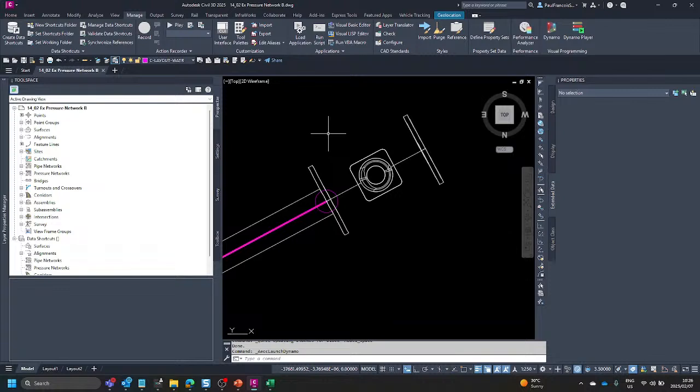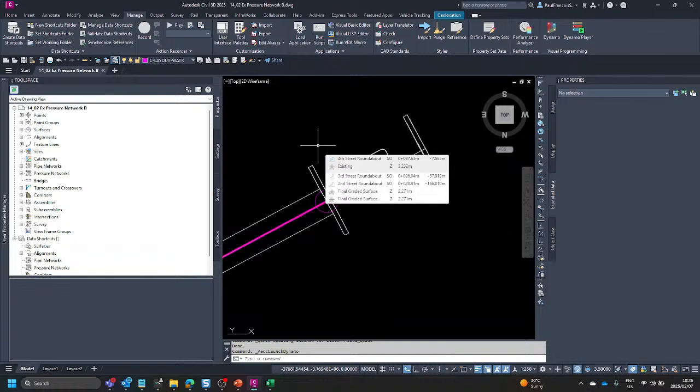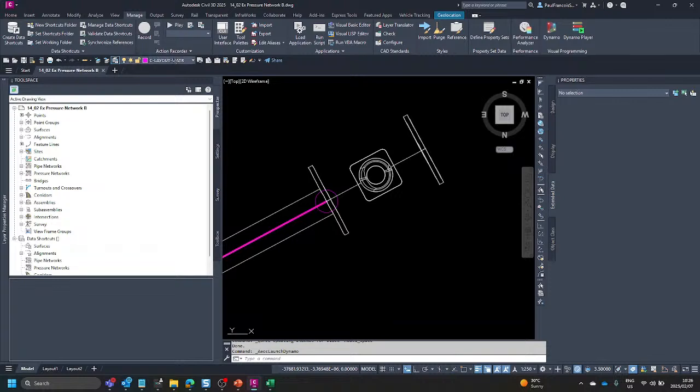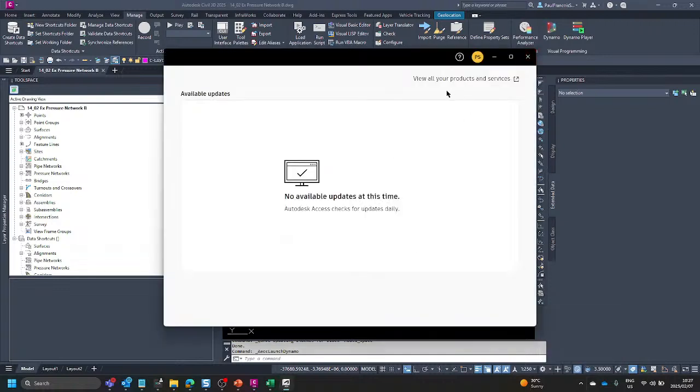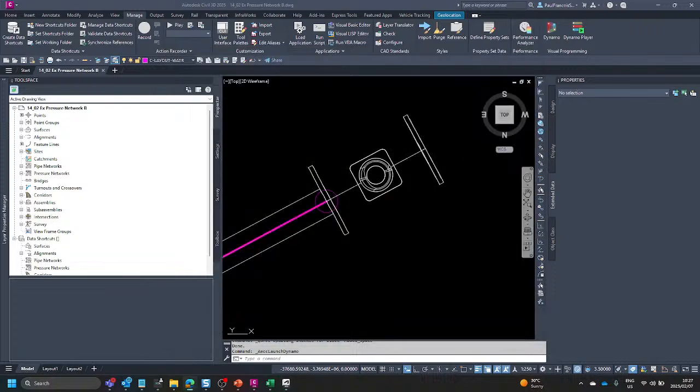And of course the next question would be, all right, provided that we can create this standard or this extended data property set for the standard, if we have it in one drawing, is it everywhere? And the answer is no, it's in this drawing. So the definition is in this drawing. And the next question is, how do we get that into a different drawing? And the answer is interesting. So I read somewhere online that the SHP export utility, which is part of your Autodesk account, could possibly help you with that. I did try it out with negative result.